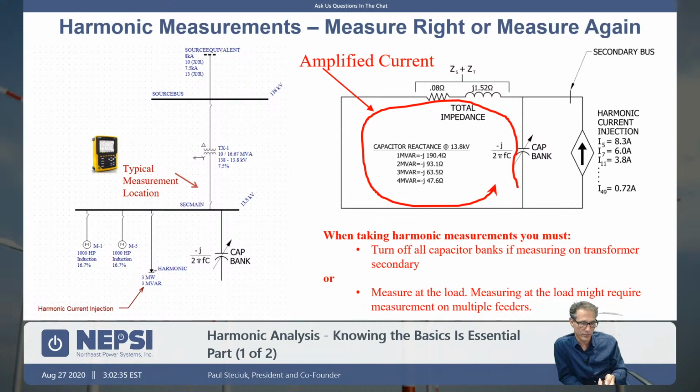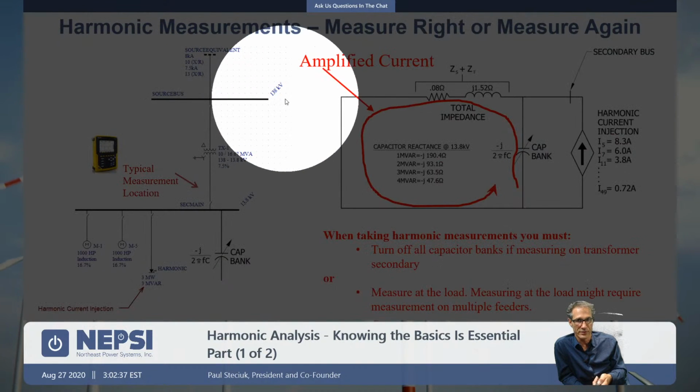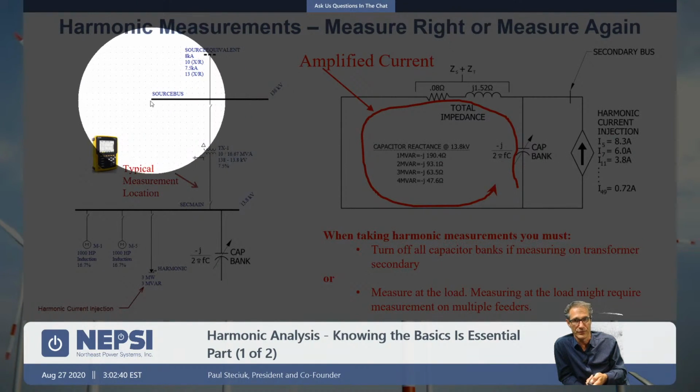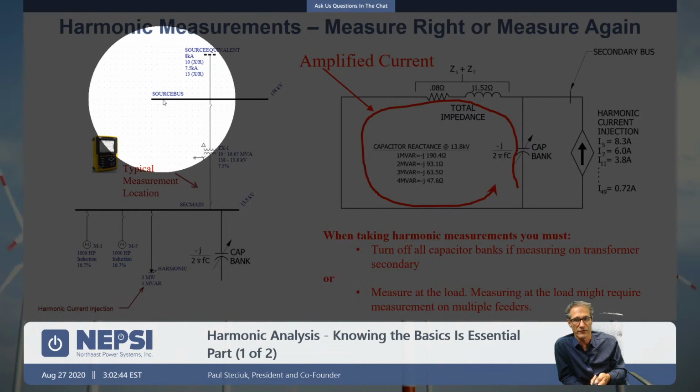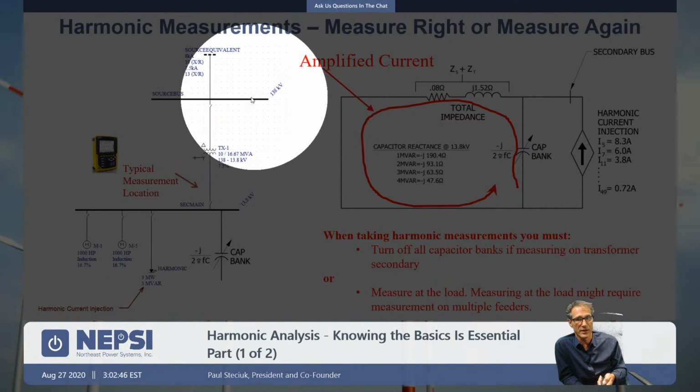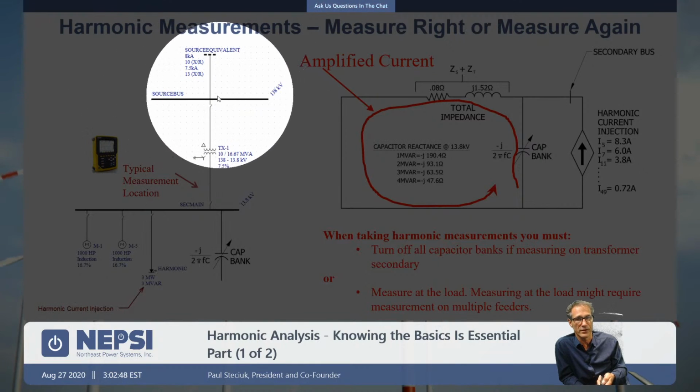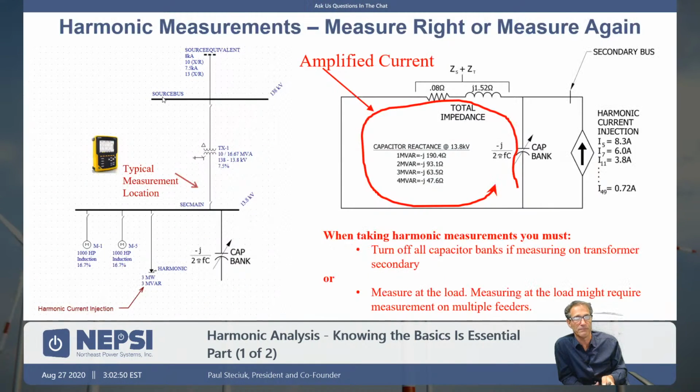So modeling voltage distortion out here is a difficult task, actually knowing what to do and how to do it. So we typically stay away from doing that. Most oftentimes I don't see studies assuming a value there because you don't know the impedance behind that voltage source. So remember, normally we're dealing with harmonic current injection creating voltage. And then it's that voltage that we're concerned about.